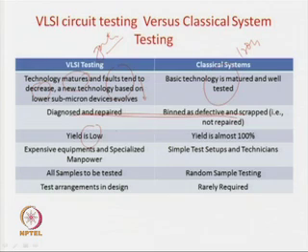Secondly, in case of classical systems, tests are very simple: you just plug it on, or even a simple technician can do your test. But in case of VLSI circuits, as you have seen for the NAND gate, it is a very tough process. You can see that you require a microscope, sometimes you require to measure voltages, sometimes you have to apply patterns. So very expensive equipment is required for this, and test arrangements, I will tell you.